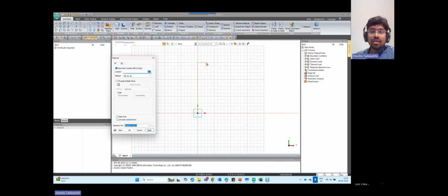So now you can see another line which was created, and this is of 3-meter width. And from here, your dam will rest somewhere over here. As we have understood, the slope is 1 time horizontal and 2 times vertical.